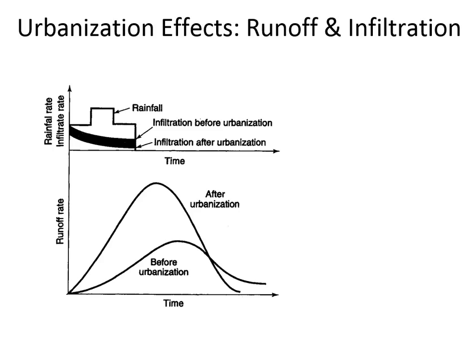And the reason for that we've already talked about is because of an increase in impervious area that comes along with development. When you pave roads, when you put roofs, those actions, even when you're just compacting soil, that decreases the infiltration capacity of what was there in the natural condition.